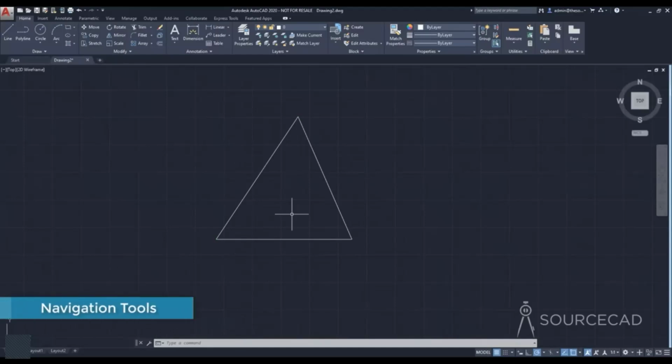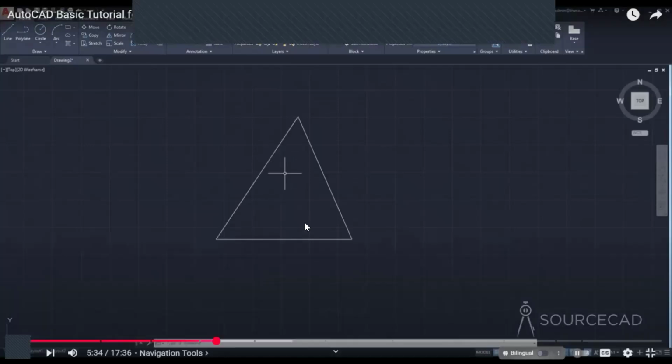So now let's talk about the navigation tools. Left click. So here we have the simple triangle. Now, if you want to navigate in your drawing, if you want to move this triangle around, then you can do that using your middle mouse wheel. So in AutoCAD, it is recommended to use a 3-button mouse, the left click, right click, and the middle mouse wheel. These buttons should be there, and to move this drawing, all you need to do is press and hold the middle mouse wheel.